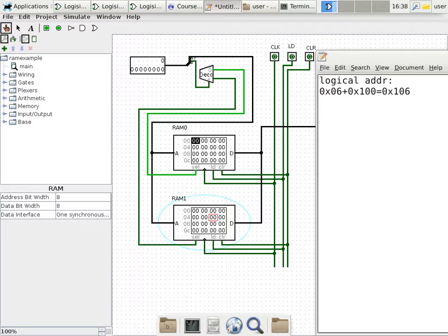Next question. This is a hexadecimal number. How do we specify that number as a binary number? Because the address bus pin is specified in binary. It's all zeros and ones. What is a 1 in hexadecimal in binary? It is 0, 0, 0, 1. Now, it's not just 1, because 1 hexadecimal digit corresponds to 4 binary digits. So the leading zeros are actually important in this case. Now, whether we drop those later on, that's a whole separate question.